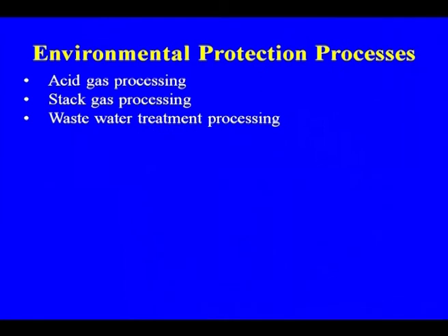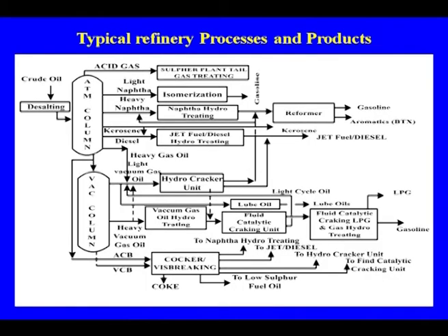This is from the environmental protection point of view: acid gas processing, stack gas processing, wastewater treatment processing. This is a typical refinery. Already I have discussed the products which you are getting. The crude oil, after desalting, goes to the atmospheric vacuum distillation column, and then the various fractions which you